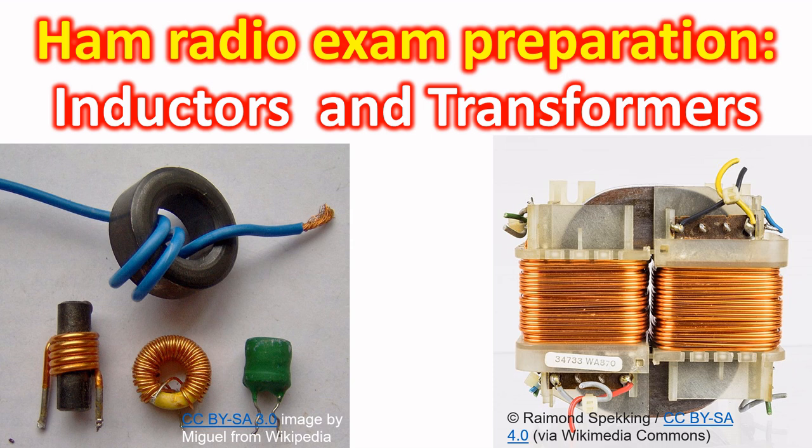The more number of turns there are in the coil, higher the inductance. Higher permeability of the core also increases inductance. Coils with larger cross-section have higher inductance. In the case of spacing between the turns of the coil, it is the other way around. Smaller the spacing between the turns of the coil, higher the inductance. The inductance in this discussion is actually self-inductance of the coil.